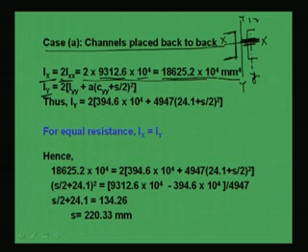So, what we will do? Iyy is there, plus that A r square, right. So, 2 into Iyy plus A into r square. What is the r value?